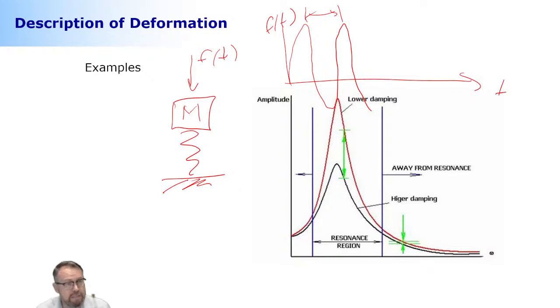And once I adjust these forces, it is possible that this frequency hits the frequency that is coming from the eigenvalue analysis. So it's a structural frequency too. Then they become the same frequency. And this is something that is called a resonance condition.